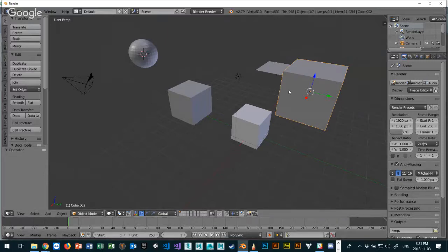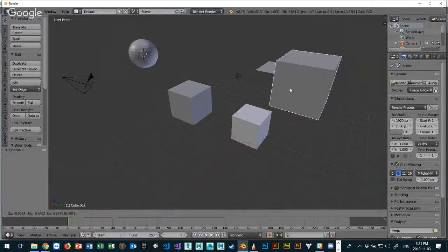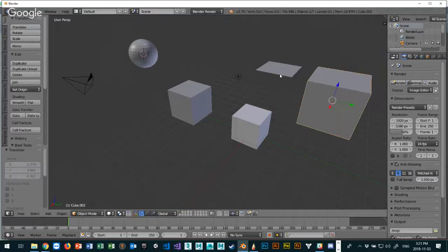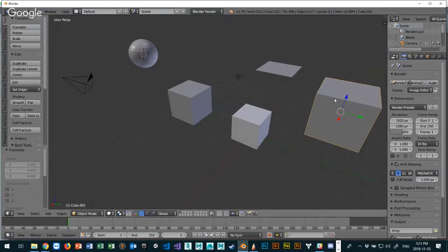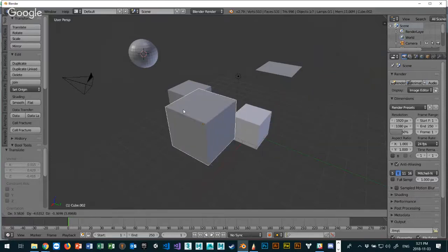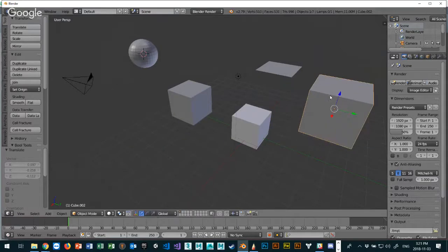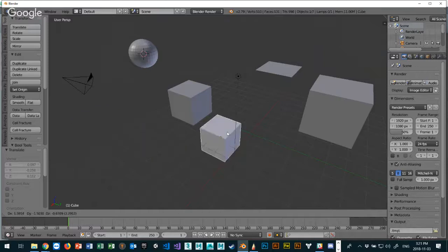One thing that people like to do is right-click on their tools and pull up a little context menu. There is no context menu in Blender. So if you right-click on an object, you don't get a context menu. What you get is selection. If I select and hold, like right-click and hold, I can move an object also in Blender. So left-click lets the object go. Right-click and hold moves the object. Left-click lets it go, and so on.